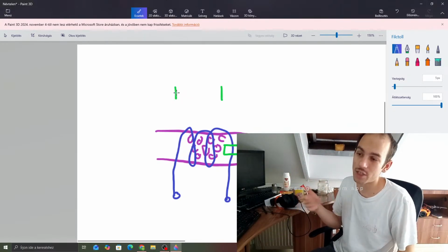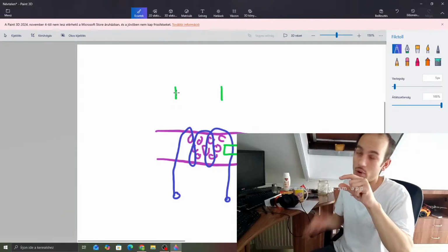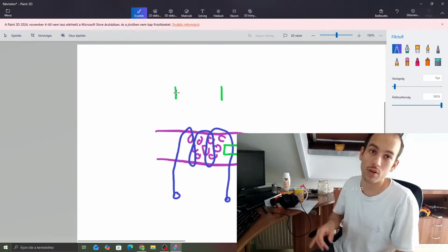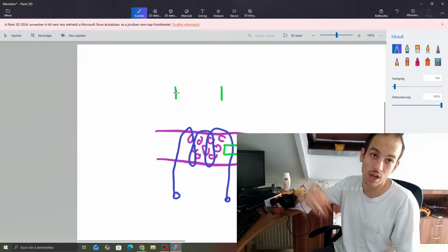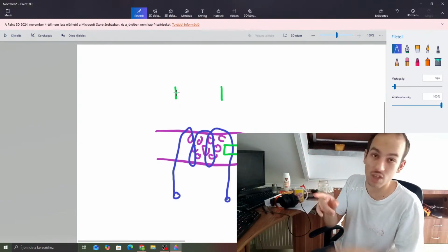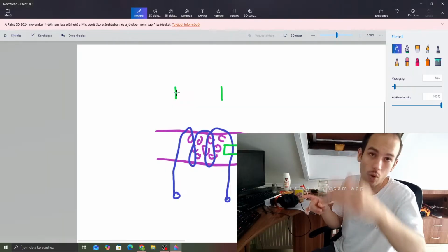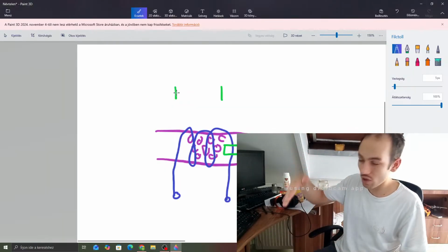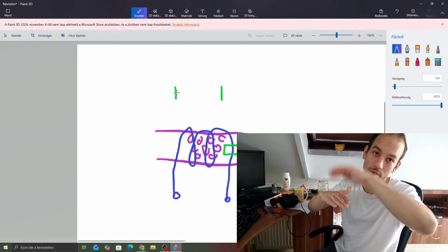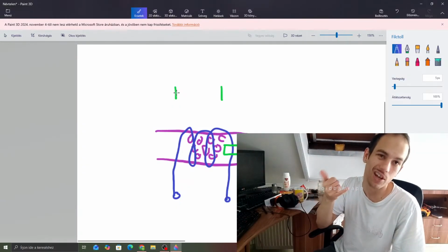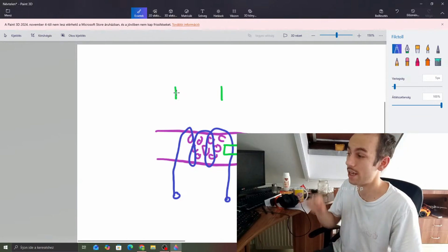That's why responsiveness in that instance is very important, to those little responses. Even hard cutting it off, because when it starts to rise, it is already almost too late to turn it off, because it will run out of the band that you want to keep it in. So that is the counter argument against responsiveness.